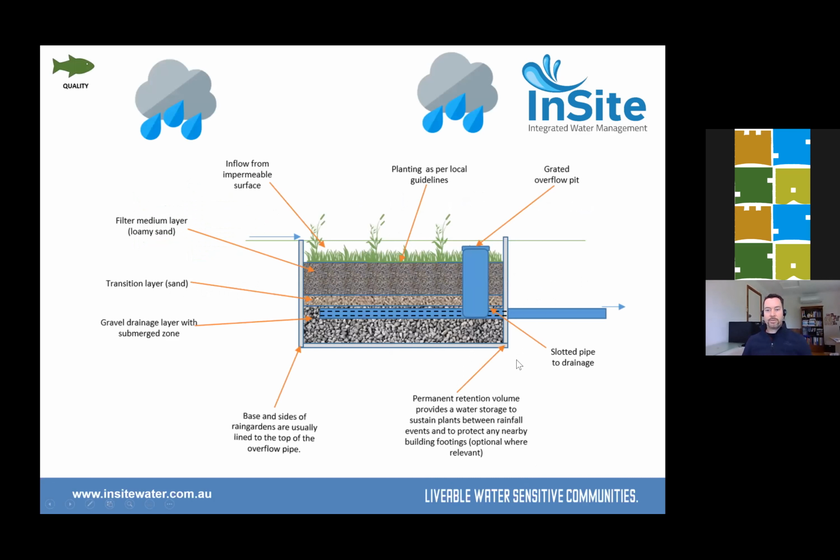So I guess the classic tool for removing nitrogen is our rain garden or bioswale. And by a rain garden or bioswale, we generally mean something like this. It has a vegetative layer at the top. There'll be a soil layer to support the vegetation. There'll be a transition layer to stop the soil being removed from the system, and then there'll be a gravel storage area. And most of the work for nitrogen removal actually occurs in the gravel, where you might have essentially slime or biofilm, as we call it, eating the soluble pollutants. But this creates great filtered flows.